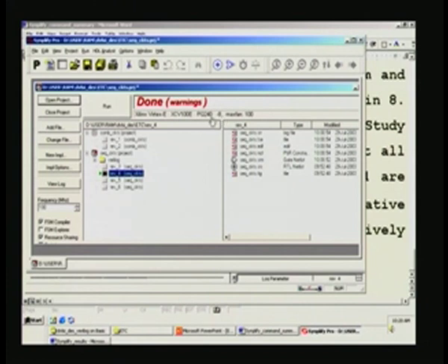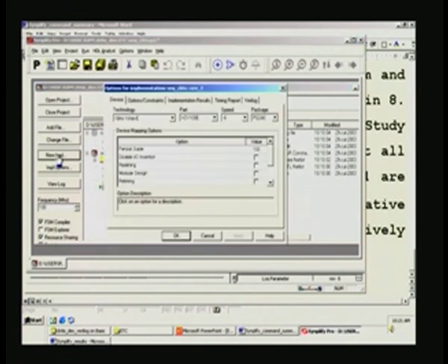And the package is 240 pins, and it is called PQ instead of HQ, I think, as we used earlier. And do not worry about the fan out, etc. What fan out basically refers to is not clear from this. It is a Xilinx Virtex-E series, and we have one more here, and this is XCV100E PQ240-6. If you have a look at this implementation, let us say new implementation, this is speed.